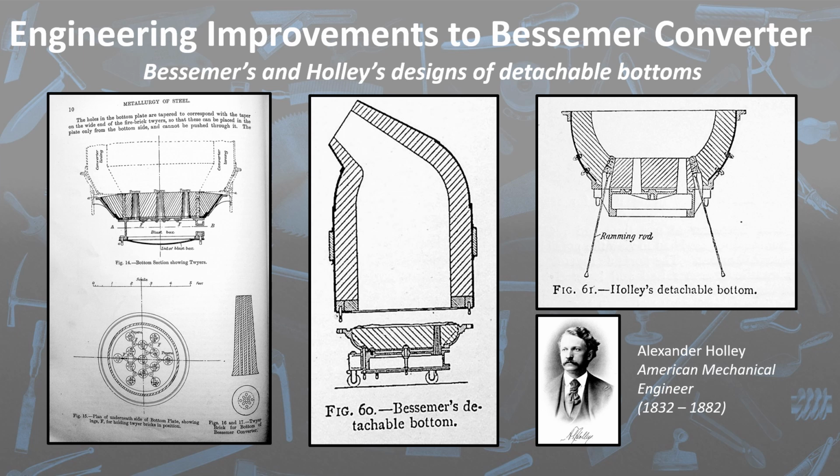Probably the main improvement was the introduction of a detachable bottom, which allowed the tuyere area to be changed when it was worn out. The base had a much shorter working life than the rest of the lining.